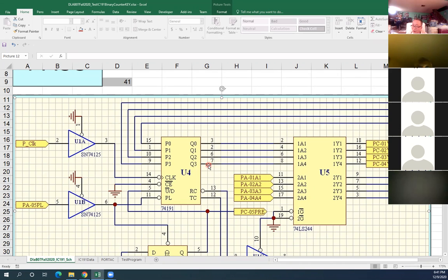That means you got pin 7 wrong. What next? You got pin 7 wrong. Are you saying pin 7 you got a 1? You want it to be a 1, but it's not. You check pin 9. You take pin 9; pin 9 is supposed to go to pin 7. Now, if you take pin 9, you're supposed to get a 1, but you don't get a 1.